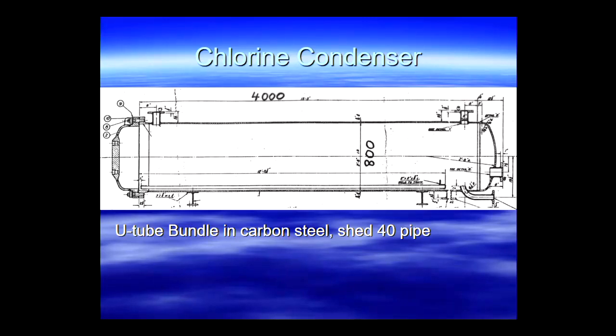Why do you want to buy schedule 160 pipe? Because the stuff they've got there is carbon steel, and I said, which is about 4 millimetres thick, got plenty of thickness. So why do you want to buy Schedule 160, which would be around about 12 millimetres thick? Hugely thick and terribly expensive tube. So what do you want to do that for?